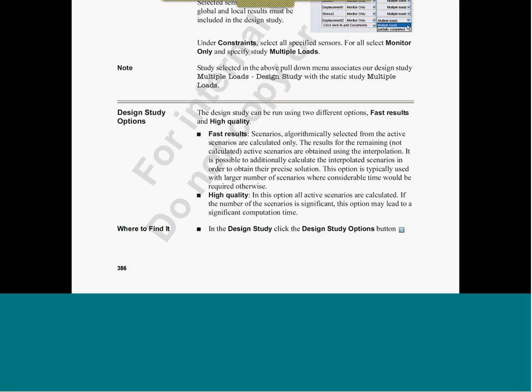But try to understand, design study is not design optimization. The optimization feature is present in simulation professional only. There the software decides the variables to be used for results, so we don't have the control. The software has an algorithm which decides those variables, manipulates them, and then gives the results. Whereas in this case, it is only variables that are given by the user. So in Solidworks Premium and simulation standard, we are getting this option only.